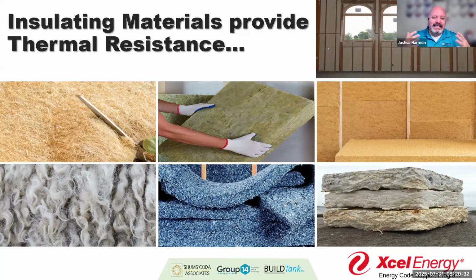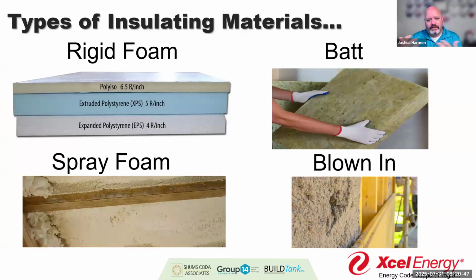They have different installation expectations. Again, there are questions about the amount of potential strapping that may go in depending on where we're placing it in a design. There's a lot of considerations to go into what material we use, but we really break it down to these four basic concepts of rigid, spray, batt, blow.